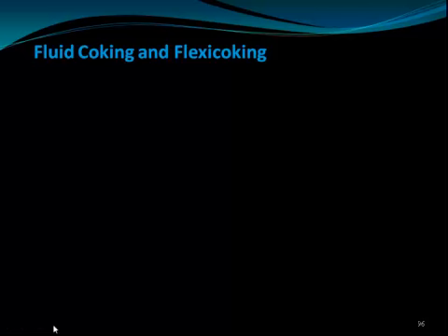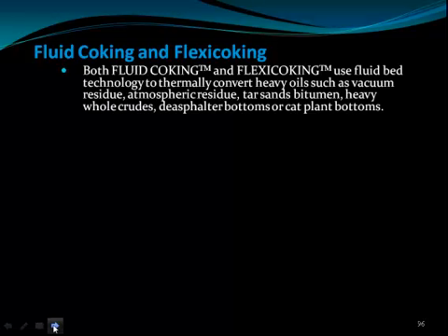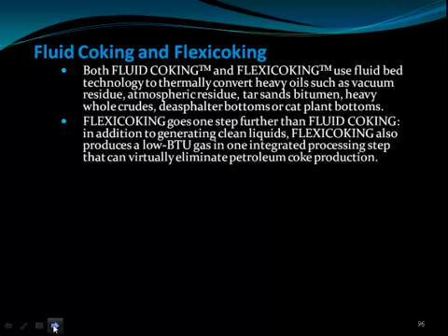So fluid coking and fluid flexi coking, that we'll see. So both fluid coking and flexi coking use fluid bed technology to thermally convert heavy oils such as vacuum residue, atmospheric residue, tars and bitumen, heavy coal liquids, these filter bottoms or cat plant bottoms. Flexi coking goes one step further than fluid coking.